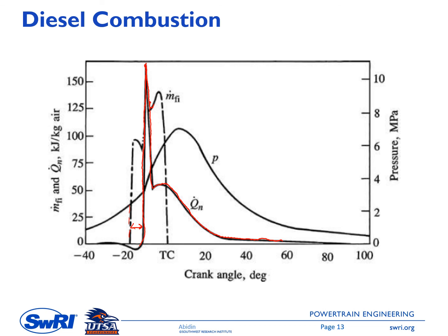And then if you compare the profile of the injection and the profile of the heat release rate, you can see here that the period of the heat release rate is longer than the period of the injection. Then, because of the combustion process, there will be a change of the slope of the cylinder pressure here. You can see it changes the slope, and this is because of the combustion process inside the chamber.